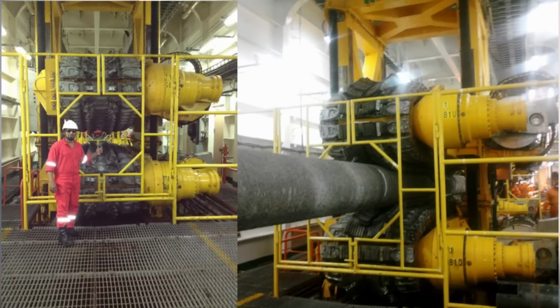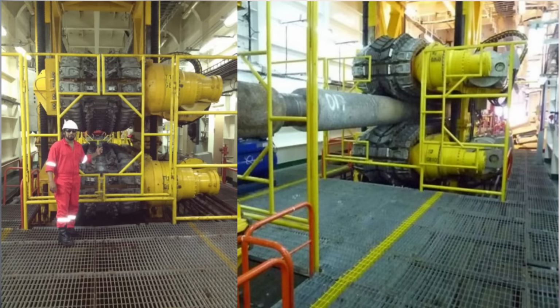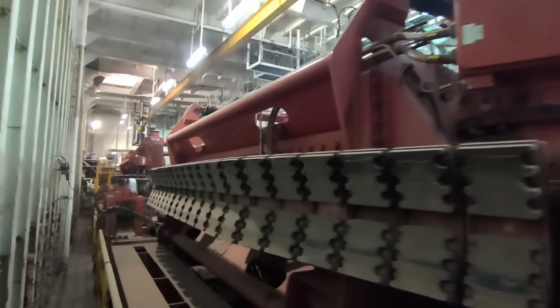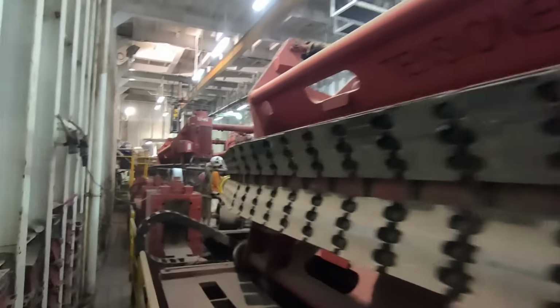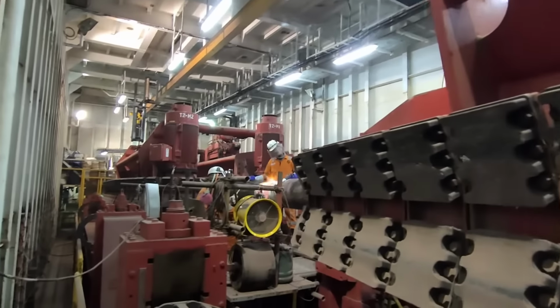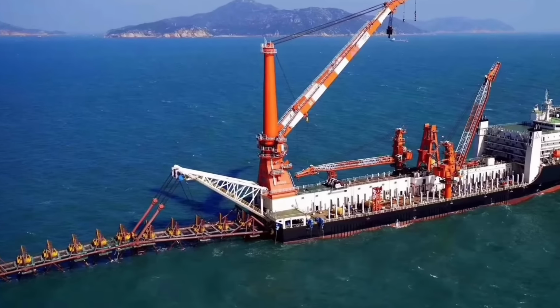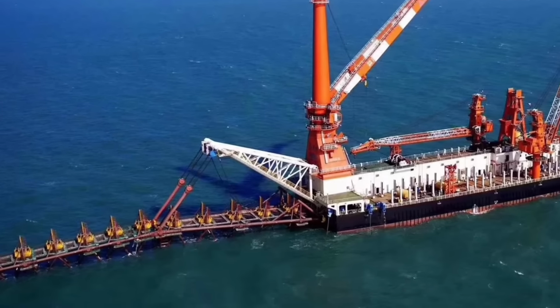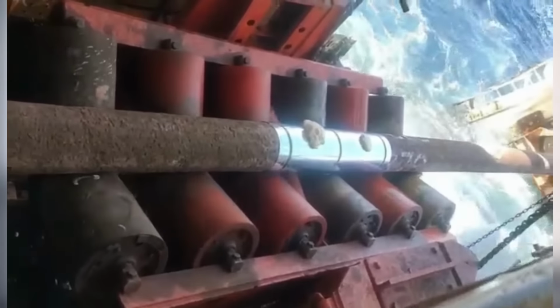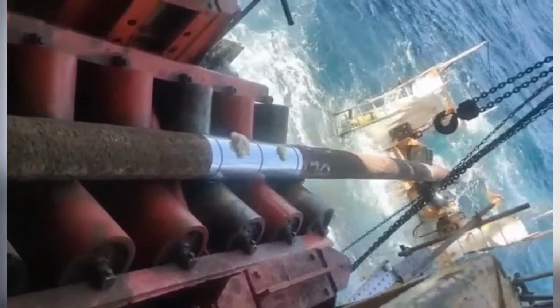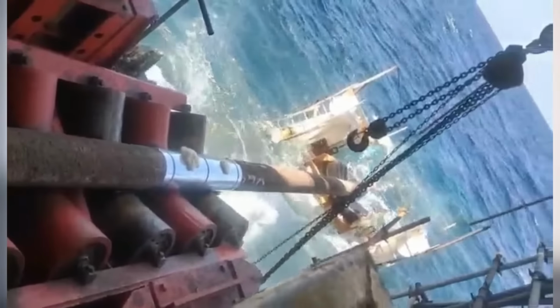There will also be a minimum of 2 tensioners which control the speed of the pipe coming out of the barge and also act as an emergency brake to stop the pipe from running out of the back. At the end of the barge there will be a long structure with rollers which helps the pipe maintain a safe profile as it enters the water.